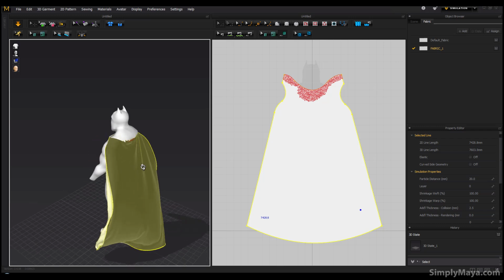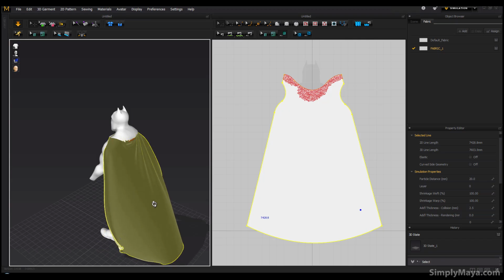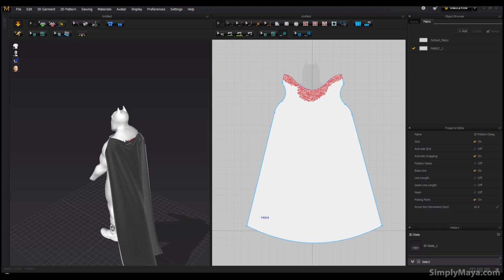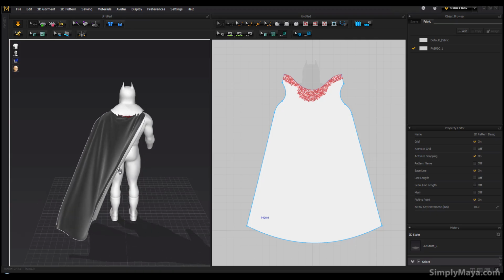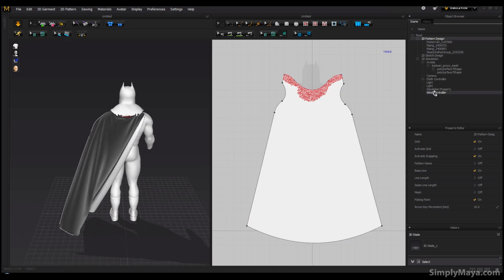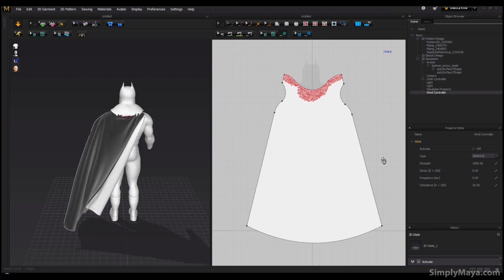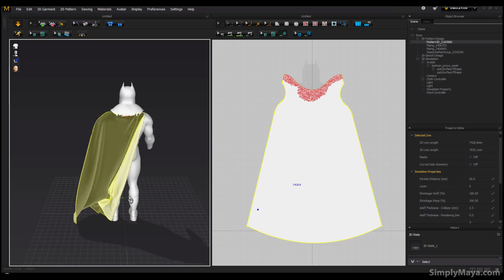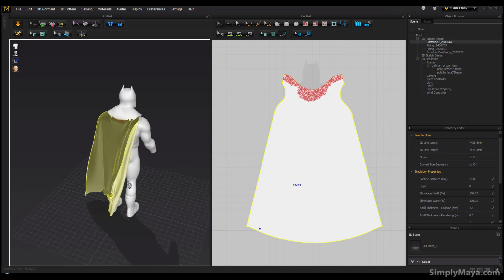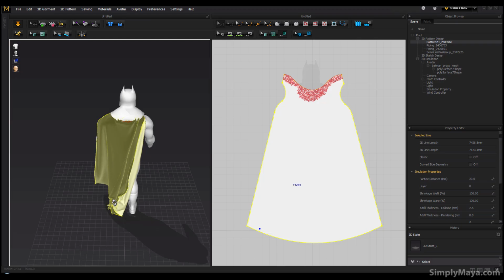And I'm just going to leave that for a second while it simulates out back kind of in a drapery pattern again. So I'm just going to pause this video for 2 seconds while this simulates out. Okay, folks, that doesn't seem to be settling down much, so you know what I think we've done? And I thought it was a bit rowdy, because I really wasn't pulling it that hard. I think we've left the wind on. And we have. So make sure you turn your wind off, folks, if you want your patterns to settle back down again, because I've got a force 10 hurricane here, and that's not going to slow down ever. So of course that was a fairly light wind, but it was just enough to keep the cloak blowing in the breeze there.